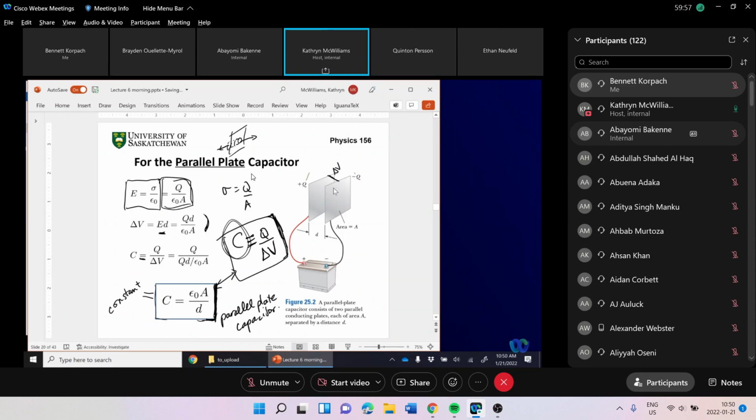The capacitance is the thing that stays the same. And the Q and the delta V will adjust each other so that the C remains the same. So if the battery starts dying, and has less ability to provide that delta V, then the amount of charge that can be held on those plates goes down too. Does that make sense? Yes, thank you.